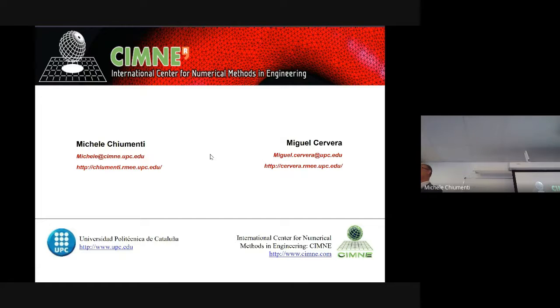Okay. Another question. How do these methods actually perform compared to the use of some generalized criteria or localization regularization? I haven't understood the question, sorry. How do these methods perform compared to the use of generalized continuum, where micromorphic approaches are used to simulate?